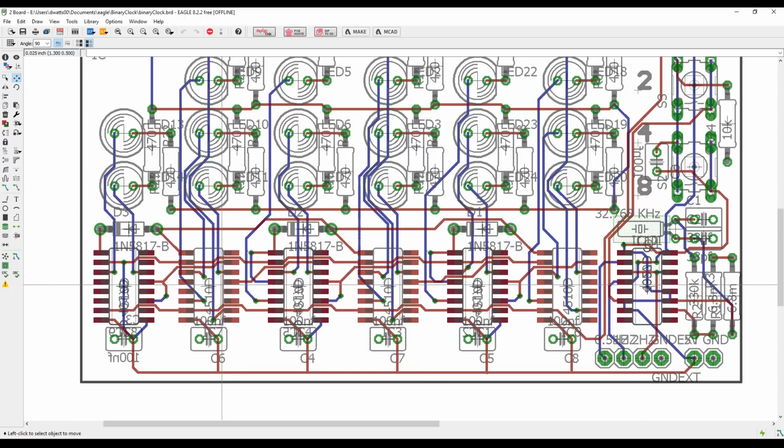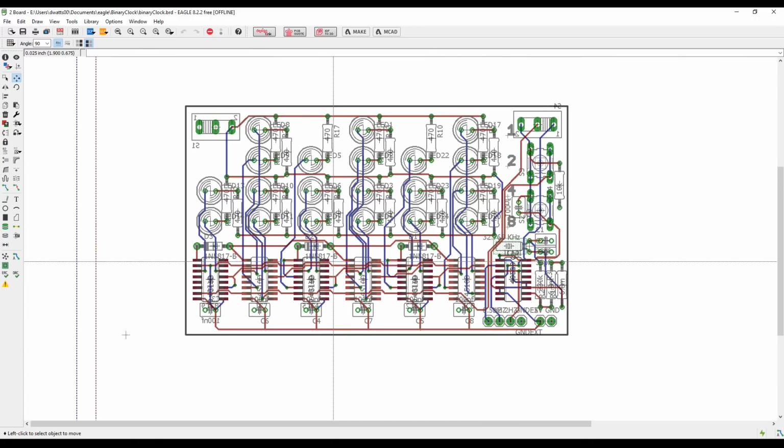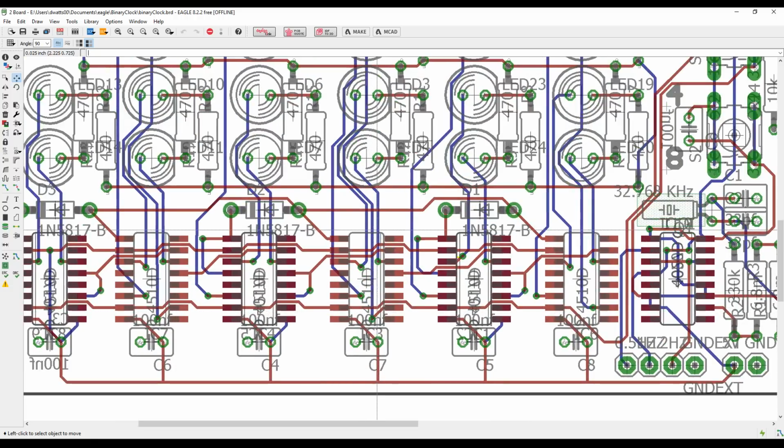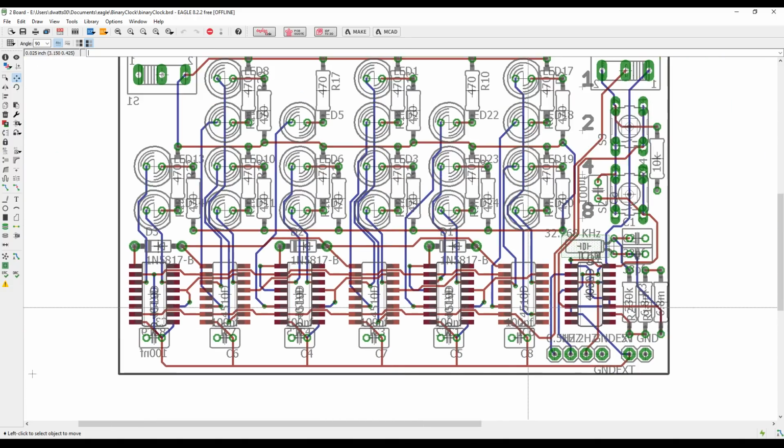So with this, I'll start from the beginning because I'm talking as if you guys have been with me on this the whole time. With the counting of these binary LEDs when they go up, we only want it to go to 9 on the minutes and on the seconds, on the sort of little digits. And I can use the chip normally to do that. It will go up to 9 and then reset, and that's fine. But on the tens of seconds and the tens of minutes, they can only go up to 5. And so I needed to find a way of resetting that chip when it got to there, but also carrying that signal over to the next set.